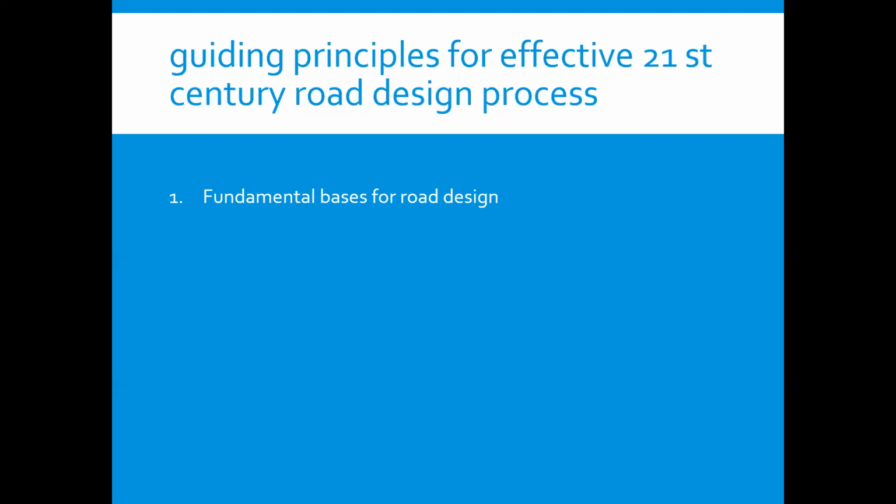I characterize these guiding principles in three categories: the fundamental base for road design, the social and public policy framework within which the process is conducted, and the necessary attributes of the effective process. These principles quite often change depending on the jurisdiction, but the fundamentals remain.